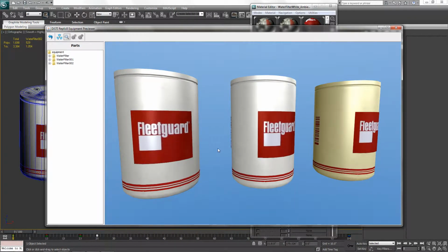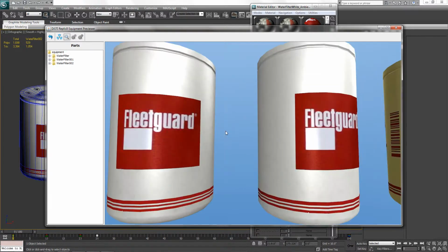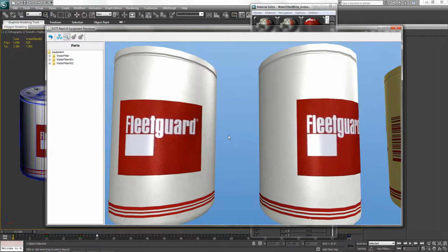So generally, you'll want to make this white to match your results as closely as possible within Max. You'll note that the default for your material is gray, so exporting with this setting will make your maps automatically a tad darker than you intended. You'll see in this file that we've created that it's just a tad darker. It's not that noticeable, but you will want to be aware of that happening.